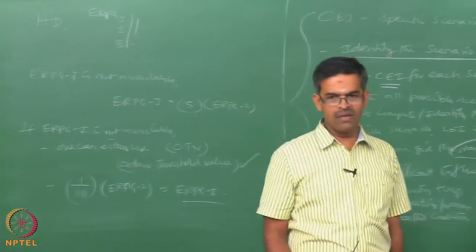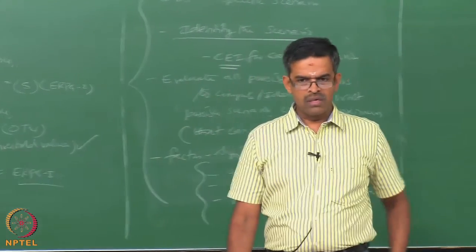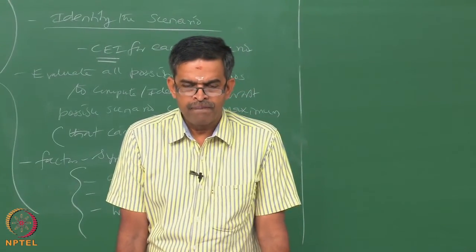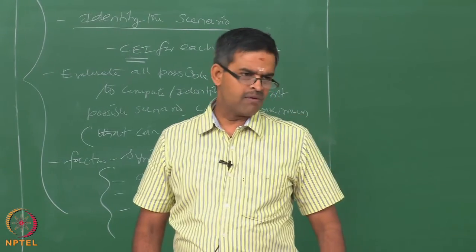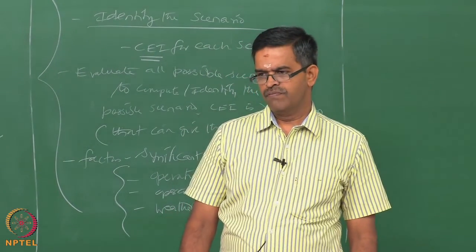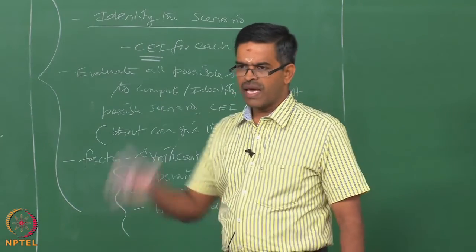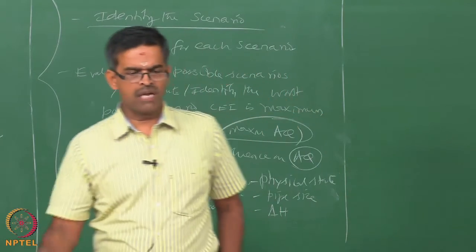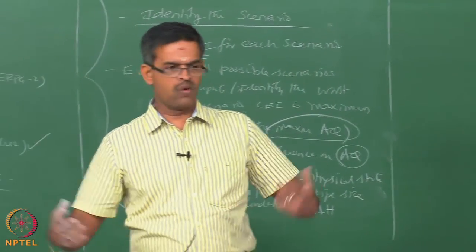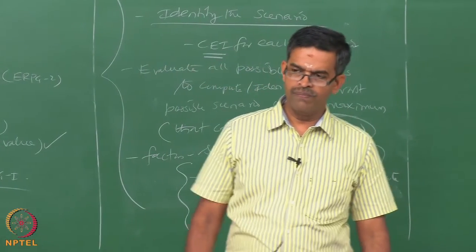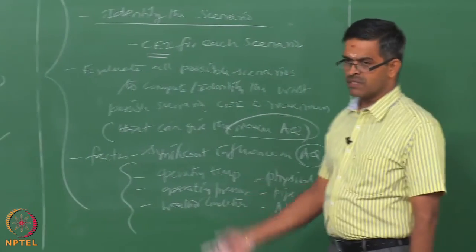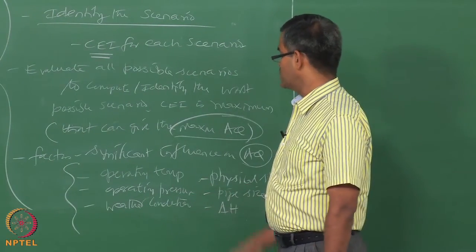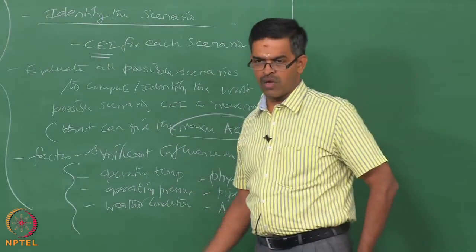Okay. So, in this lecture we learned how to actually do a chemical exposure analysis, how to estimate the chemical exposure index which is given by Dow's method. We have also understood how the gas and liquid concentrations can be equally handled by different equations which are empirical in nature. What are the factors that can influence the hazard distances? What are the factors that can influence the chemical exposure index or AQ value?